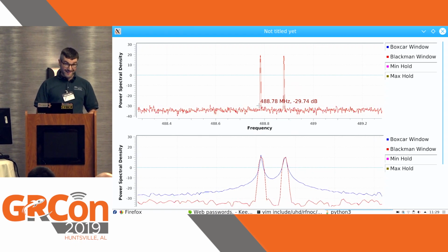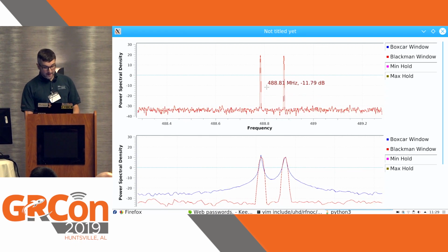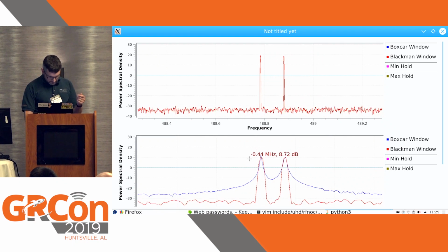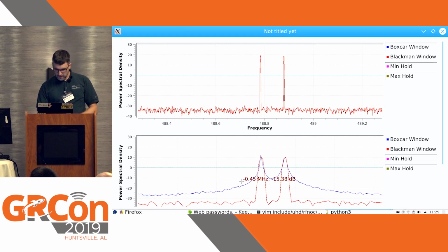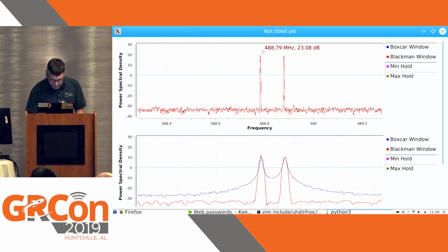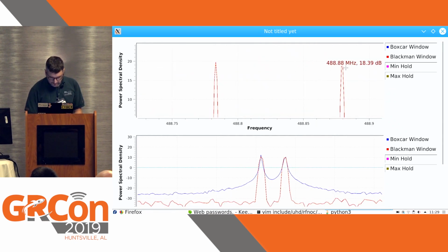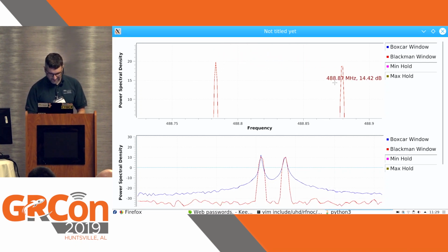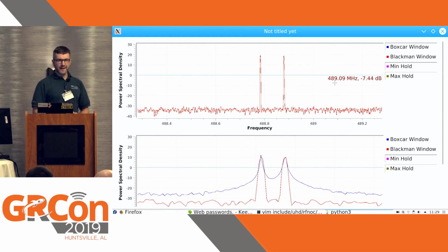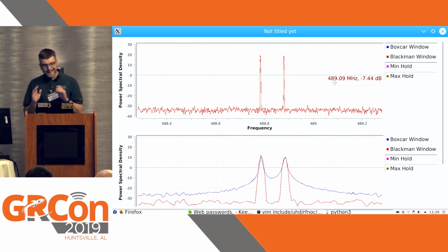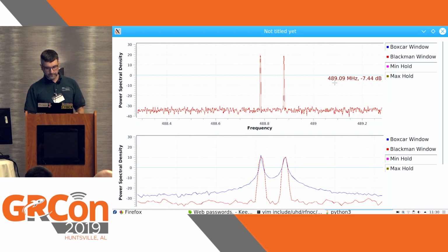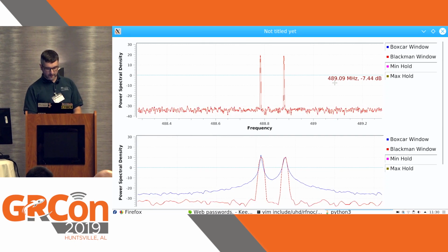Because I said I put in the exact same signal twice. This here is 50. Here, if you go by your logic, it's 40. And here, you have to zoom in to see that, but this guy is also a little bit lower than that guy. So this would be 50, and this would be like 47 or something. Doesn't really make sense, okay? How can the signal to noise ratio be different? That's because the parameters of my spectral estimation, or my estimator, actually matter in this case.